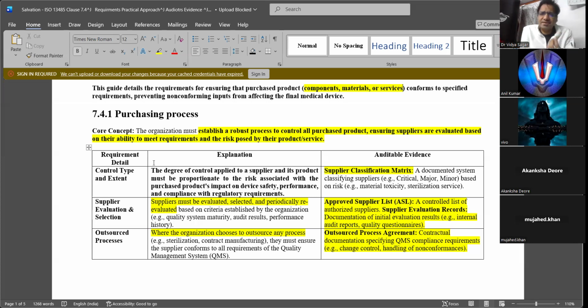See, in life-saving devices, you will have a very narrow range or narrow standard deviations like 0.2 mm or 0.3 mm, unlike class 1 or class 2 devices. And you need to be very careful in the material selection and also verification. So these are high-risk materials. You need to grade your supplier based on the risk of the material which you are purchasing. Suppose I am purchasing some plastics for the hub, or something like cotton, or the needle tubes, something for the welding process. Okay, that's fine.